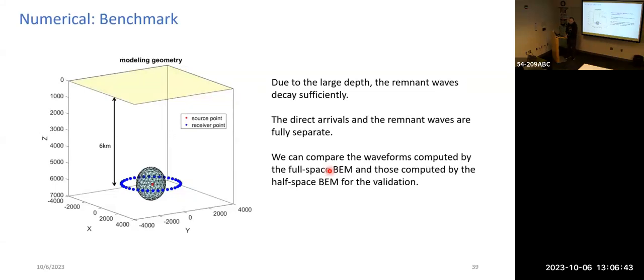I assume you have no absorption, so your model is purely elastic, no attenuation. Then extinction should be equal to scattering. So something like adding up the energy around the outside of the domain and comparing it to the scattering energy. If your error is 0, then you can be sure your model is convergent.